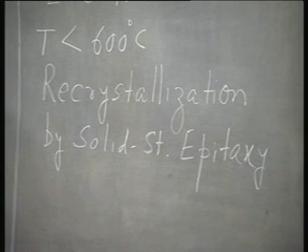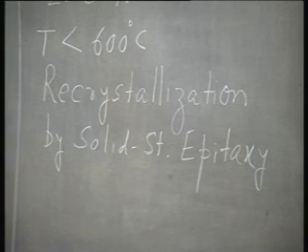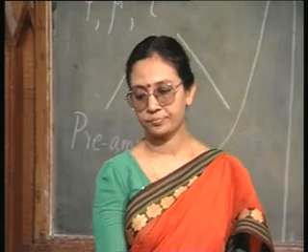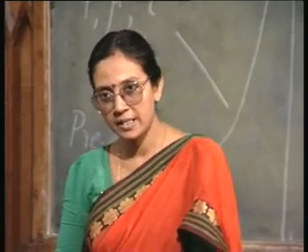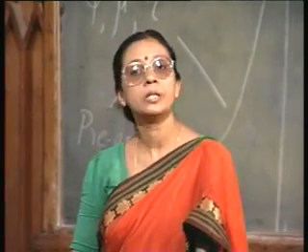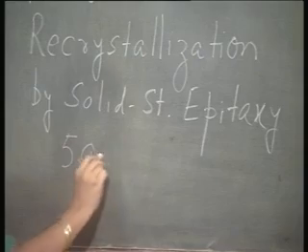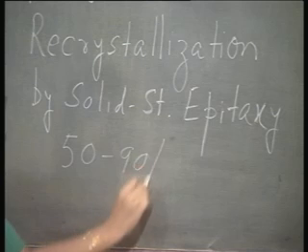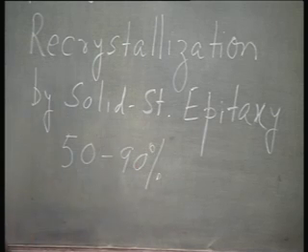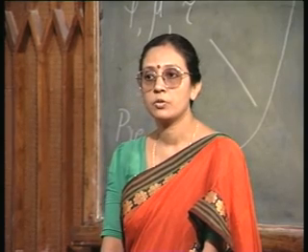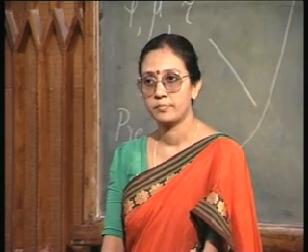So, what you have in this temperature range is recrystallization by solid state epitaxy, and carrier activation can be up to 90%, 50 to 90%. Remember, even now considerable amount of damage will remain there.